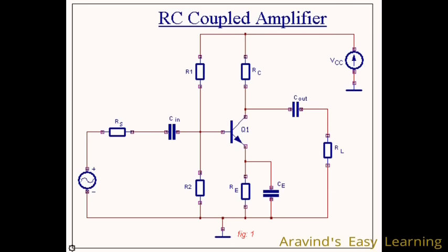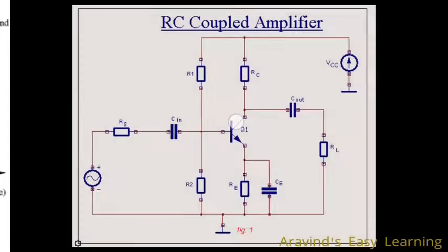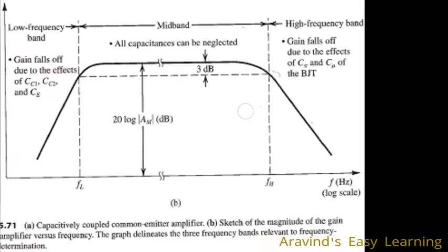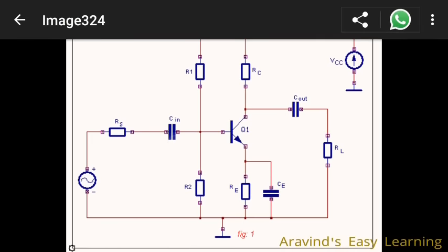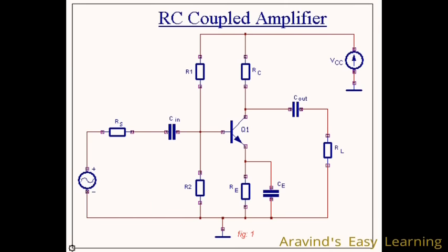Okay, so as I said, we could produce this effect using only a transistor, but why are all these elements present here? There are resistors, capacitors. Why are they present? See, in the broad sense, there are other factors we need to consider. In a transistor circuit, there is something known as the operating point, and it is essential to keep the operating point stabilized, and that is why we study different biasing stabilization circuits, like the voltage divider bias used here.